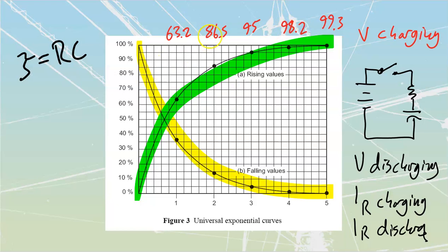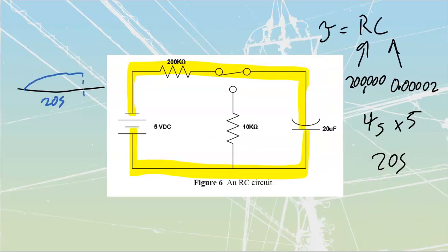That one I do have memorized. I don't know why I just wobbled on that one, but it is what it is. So 4 time constants into here, we would be at 98.2% of our voltage that we are going to go and have. So it says, what would the voltage be across the capacitor after 4, oh shoot,